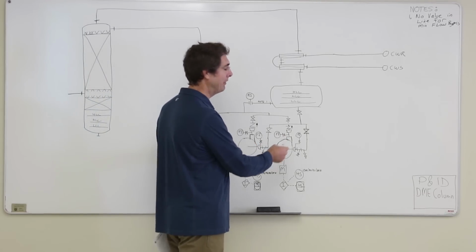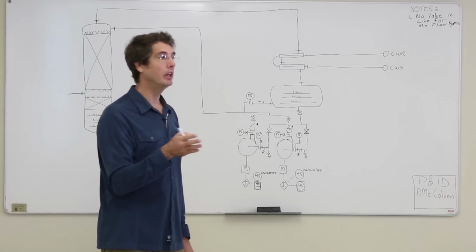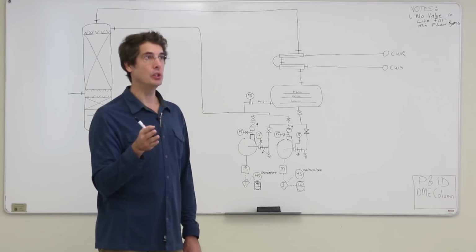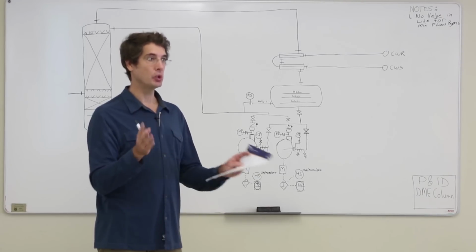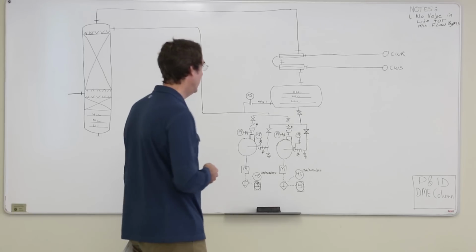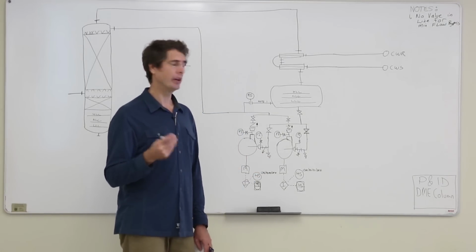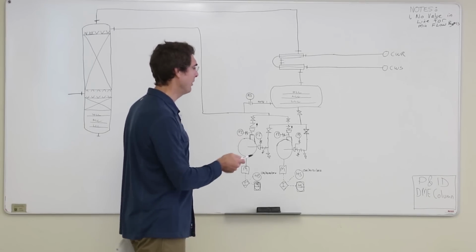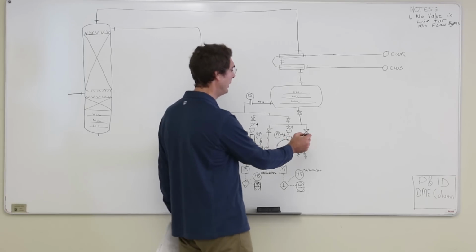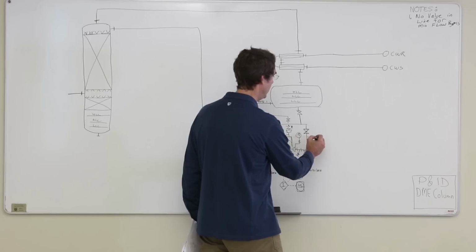If you needed to put a relief valve in, the only reason you need to is if you have a positive displacement pump, or you have a fluid that is going to thermally expand due to ambient temperatures. So if you have a fluid with a high thermal coefficient of expansion, some of the fuel oils have that situation. Most of the chemical plants, like methanol and stuff like that, they don't really bother too much about it. But if you did need to put a relief valve in, Seb, what you do is you